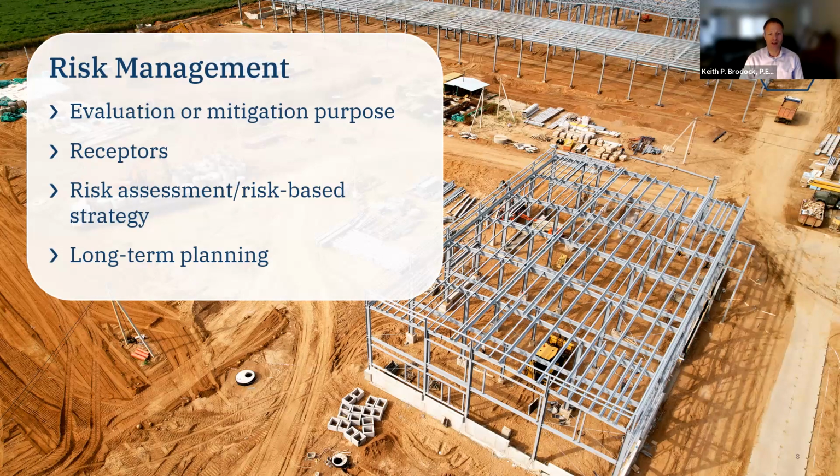And this goes back to the CSM, the conceptual site model that Susan discussed earlier when talking about the vapor intrusion pathway. We want to make sure as part of that CSM evaluation that we know what the building is currently used for, or as you see in the slide here, what the building might be used for after construction, because that's really going to change how we are evaluating the building, how we're designing this investigation. And if it's necessary, it goes to how we're designing that control measure. We may adjust our investigation or our mitigation approaches depending on whether it's a daycare versus a commercial building.